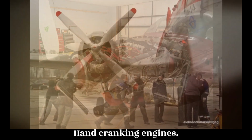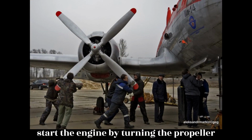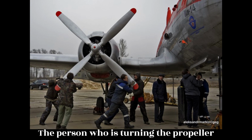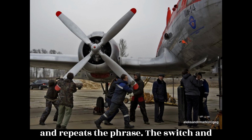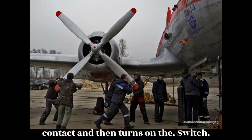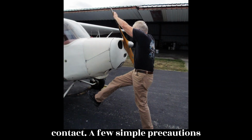Hand cranking engines. If the aircraft has no self-starter, start the engine by turning the propeller by hand, propping the propeller. The person who is turning the propeller calls, fuel on, switch off, throttle closed, brakes on. The person operating the engine checks these items and repeats the phrase. The switch and throttle must not be touched again until the person swinging the prop calls contact. The operator repeats contact and then turns on the switch. Never turn on the switch and then call contact.